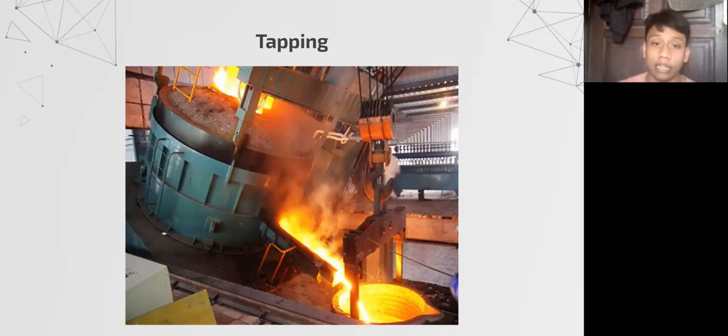But the electrical arc furnace itself will be turned around to be prepared for the next charging and for the next heat. This turnaround is the highest dead time, which means the electrical arc furnace has no power and is not melting. So what we do when we turn around the electrical arc furnace is raise the roof and the electrode, and we inspect if there is any damage from the process that has been done before. After that, the electrical arc furnace will be repaired if necessary, and if not, it will be prepared for the next charging process and the next melting step.